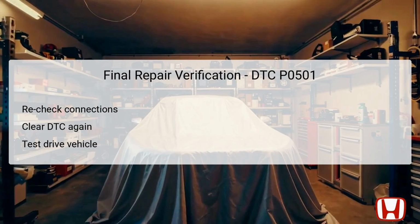Once the DTC is cleared, it's vital to conduct a test drive under conditions replicating those when the DTC was triggered. Pay attention to any warning lights and monitor performance. The goal is to confirm that the DTC P0501 no longer appears, indicating that the repair was effective and the vehicle is operating as intended.